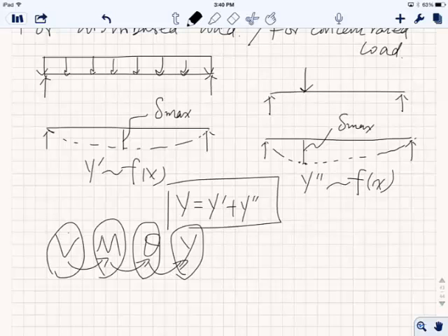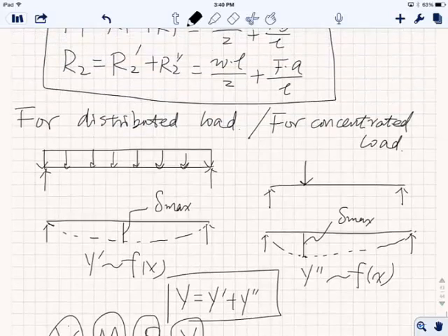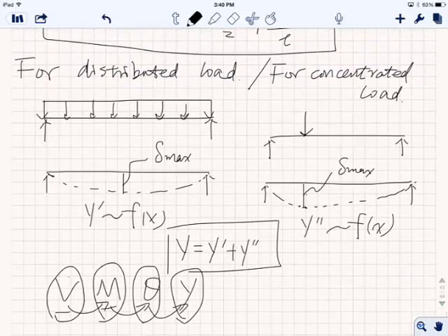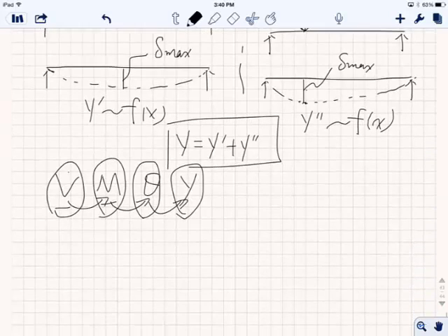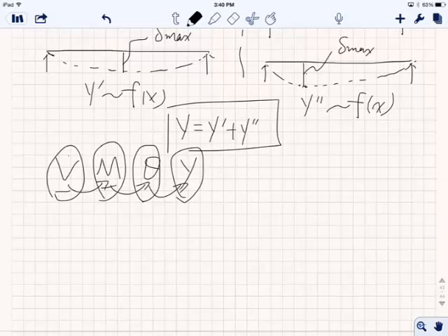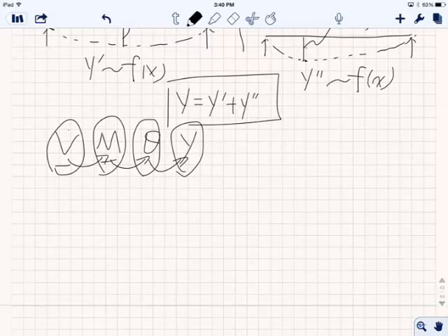And we're pretty confident we can find these first two. That's what we did before, right? Now again, this problem, the key concept is the superposition. So you consider these two cases separately and add them together, right? It's not too complicated, right? It's just two different loadings, so you have to do the superposition to add them together, okay? All right, so let's see over here.